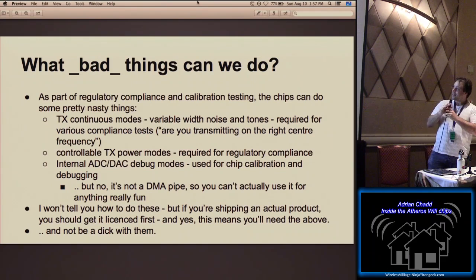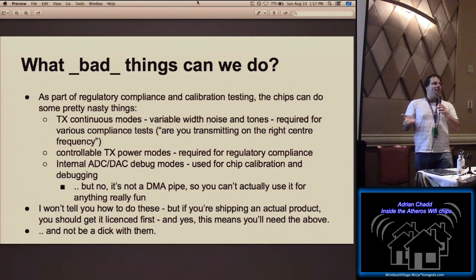The other interesting thing is you get to put the NIC into debug modes where you get to inject and receive raw ADC data. It's useful for doing calibration, but it's not useful for doing any other kind of spoofing, at least not from what I've been doing. Most of the time you're feeding the chip a sine wave, and you're trying to calibrate the chip to make sure that what the DAC gets back is an accurate sine wave. So we put the chip in the debug mode, feed it a constant sine wave, pull out 4K of sample data at a time, and make sure that the chip is doing its thing.